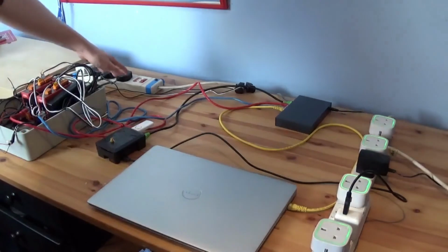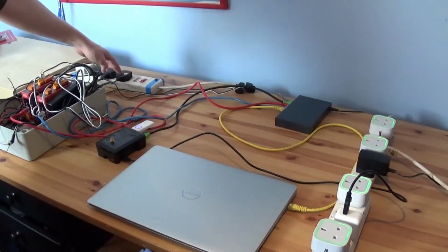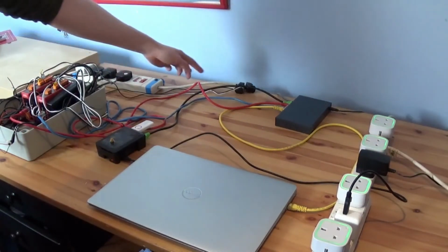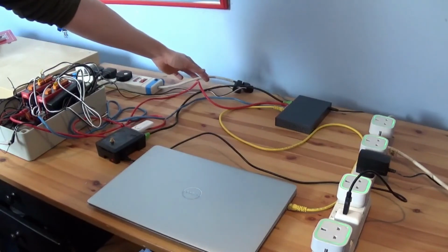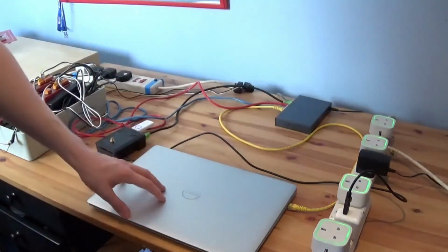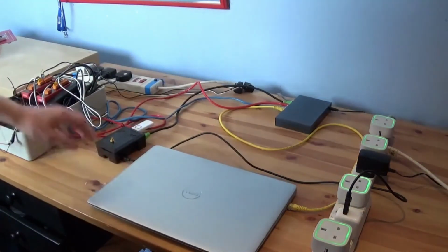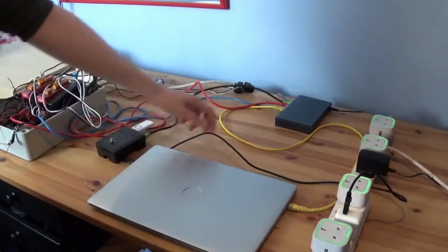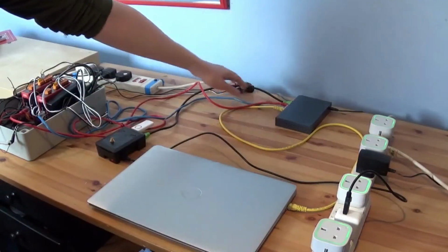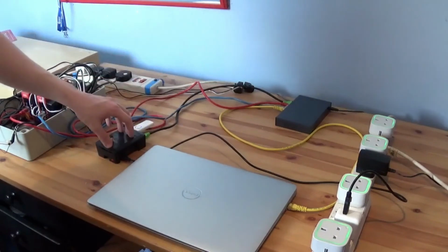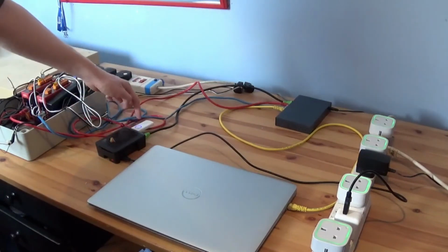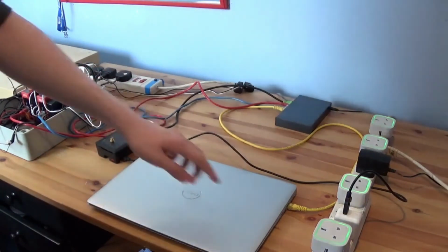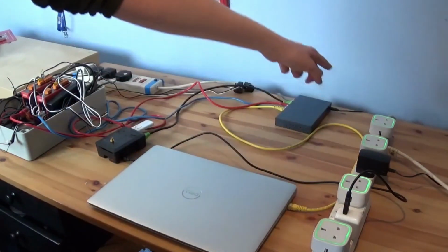Power to the meters is obtained from this outlet, as well as a voltage reference for the meters. The current transformers are clipped onto the shielding of the live wire here. The database is housed within this laptop, but the smart meters and the database connect back to this network switch, which is also connected to the Raspberry Pi hub. The Raspberry Pi hub then has a Z-Wave USB antenna to communicate with each of the smart plugs.